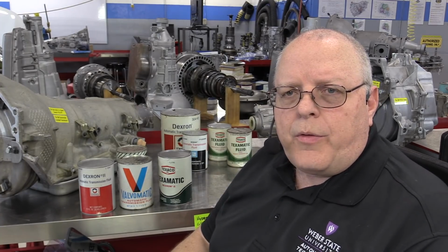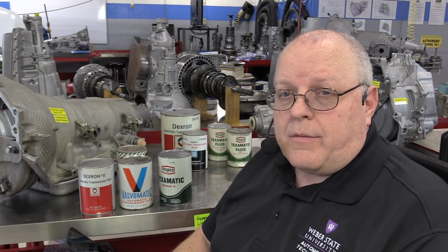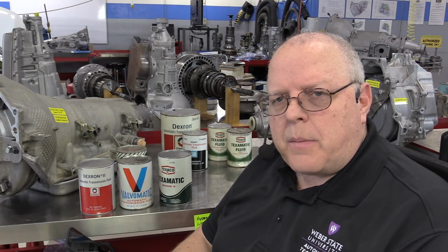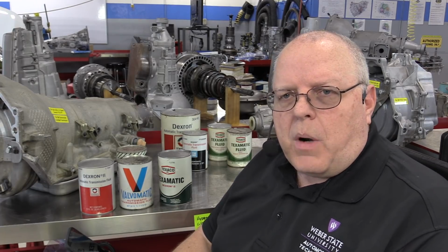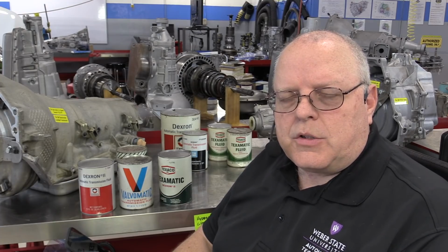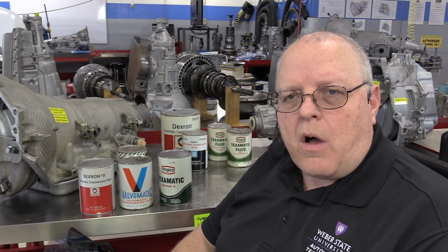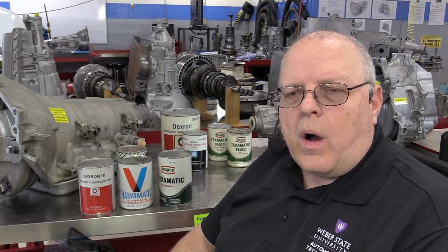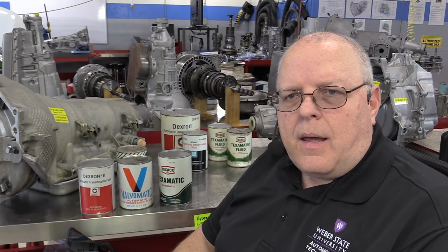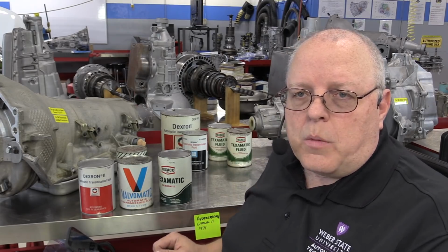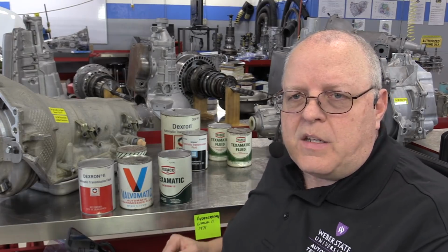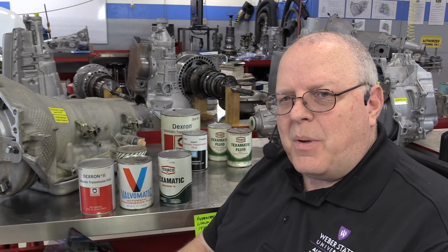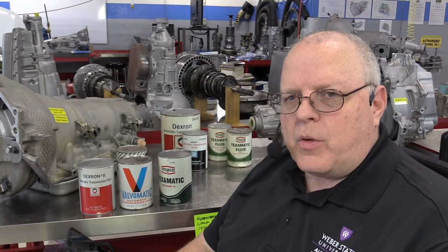So one of the ways to improve fuel economy was to get an overdrive transmission, go to a 4-speed overdrive, and to get rid of the slipping inside of the torque converter by installing what's called a torque converter clutch. And the torque converter clutches back then would lock the engine's crankshaft to the input shaft of the automatic transmission while you're driving down the road at a steady speed. And it would improve fuel economy because normally you would have a slip or a speed difference of 200 or 300 RPM. A whole new batch of technologies had to be invented to meet these corporate average fuel economy standards.